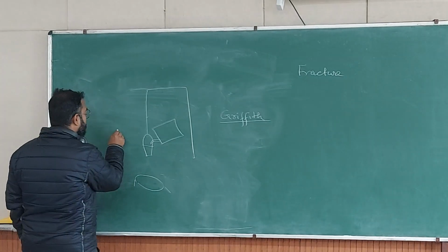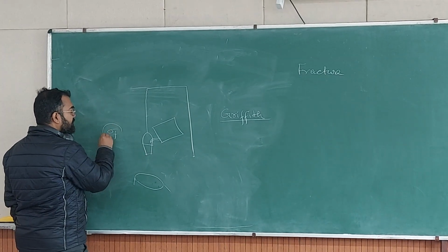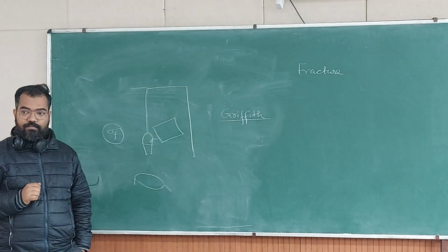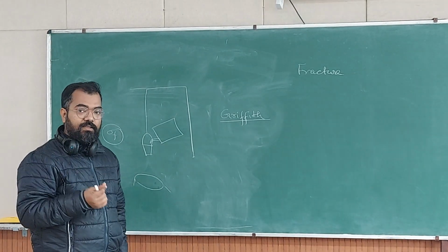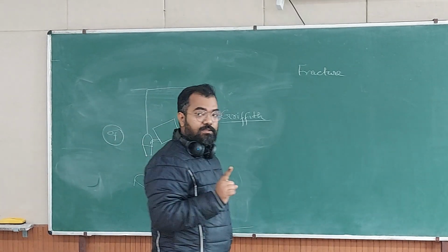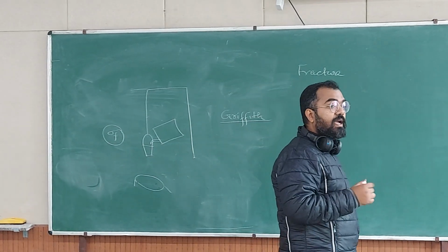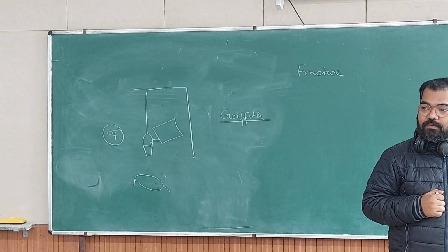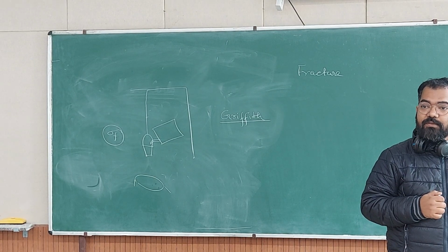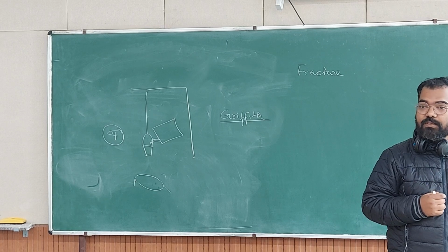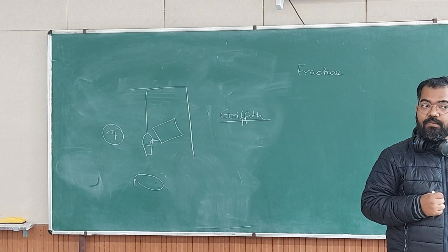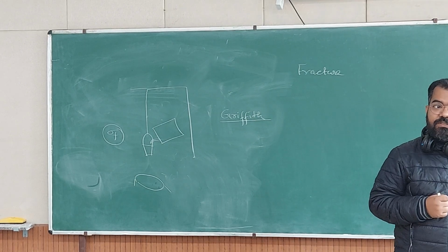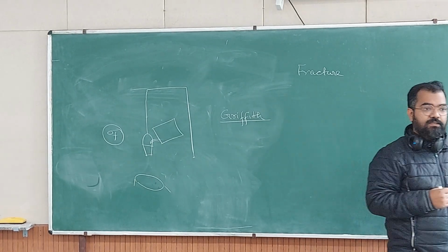The result of the study was that this stress was different for different diameters of wire. If you change the diameter of the wire, not the force, the stress will be different. Why will it be different? It's the same material. If you are changing the diameter, why will the stress be different? Change of surface area. Surface area? What is the relation of surface area with fracture stress?